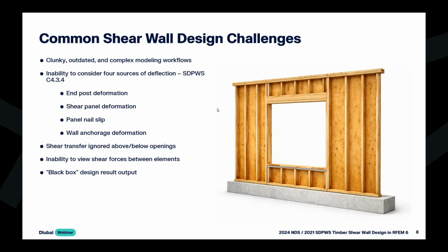Additionally, when we talk about these analytical approaches, shear transfer is typically ignored above and below the openings. In addition, we also have the inability to view shear forces between elements. For example, when we're talking about the panel nail slip, this is how the sheathing is connecting to those stud elements. We're not necessarily able to see so easily what these shear forces are between these two elements.